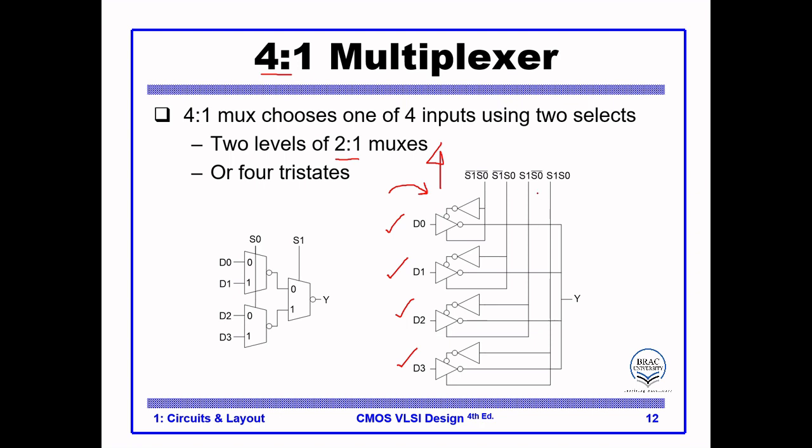And we use two signal pins S0 and S1. So if we have 0 0 in S1 and S0, this signal will be 1, but all of the others will be 0. So this buffer will activate and will output this one, but all of the other buffers will be in Z state. So they will be disconnected from the output or will be in a floating connection like this.